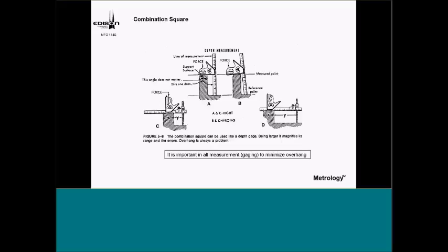Some more uses. Here I share with them, you definitely want to watch overhang, the springboard effect, especially when you start using a dial indicator. And watch your force.